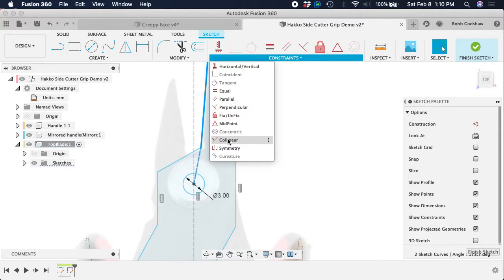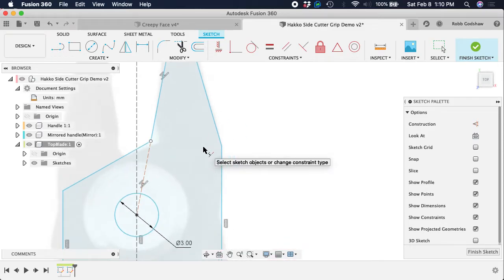And what collinear says is, two lines can have no relationship. They can be parallel, which means they're going in the same direction, that they're never going to cross, but they don't have any spatial relationship to each other. So this is parallel. Or they can be collinear, which means that these two line segments are actually part of the same line. They could be overlapping, they could be on top of each other, they could be miles apart. But no matter what happens, they're the same line. So like co-working, whatever means with. Linear means I guess pertaining to lines. I don't know, liney. But if I select collinear, you'll see that kink went away.